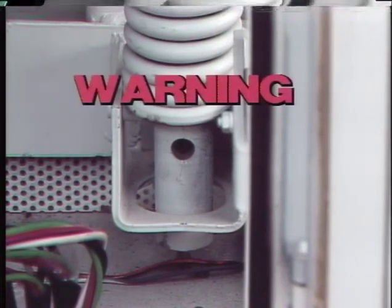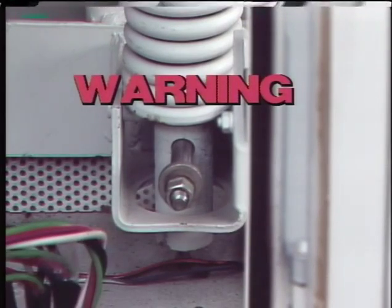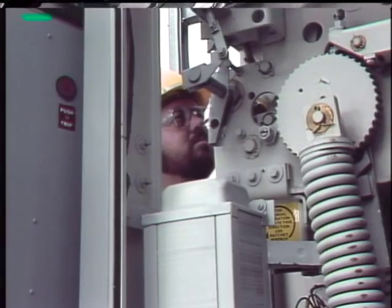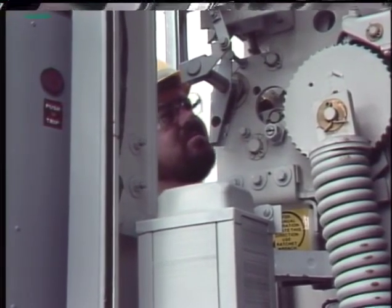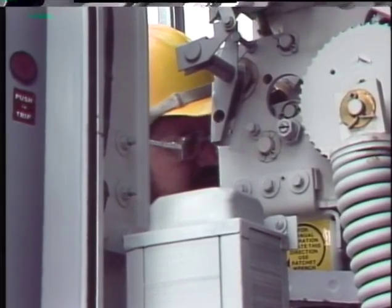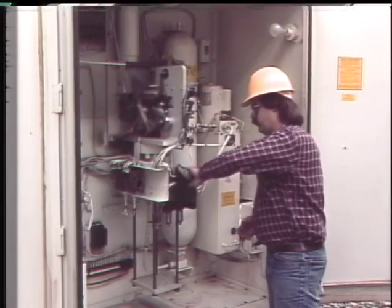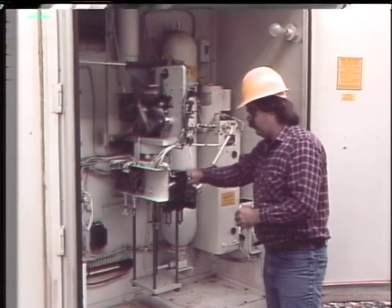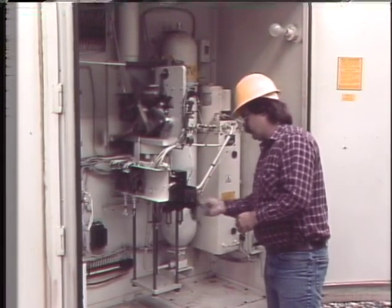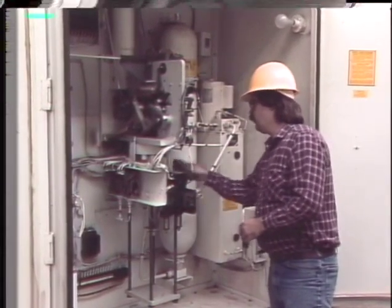A word of warning is needed here. For most mechanism maintenance, the source of stored energy should be blocked or discharged to keep the breaker from closing and to prevent injuries from accidental operation. General maintenance for breaker operating mechanisms is similar to general maintenance for the breaker itself. The tasks include inspecting for damage, checking adjustments, and cleaning. A little bit of dirt might not seem like a big problem, but it can cause friction and wear that may slow the mechanism down or prevent it from working and can reduce its effective life.